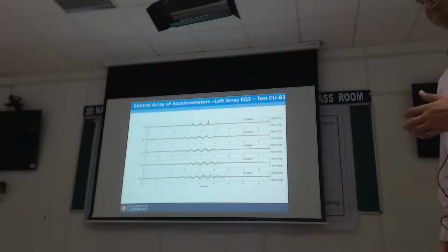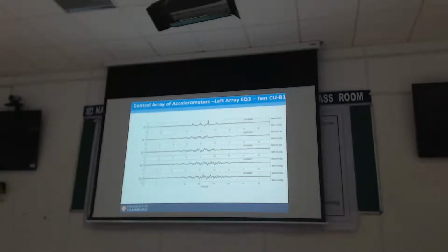Then, in order to make this slope move, we hit it with a secondary earthquake, which is 0.25 or 0.3 G. It still did not move. Then we hit it with the 3rd, 4th, and 5th earthquakes, increasing the strength. I'm going to show you the results of this 3rd earthquake, because here we are applying an input motion of about 0.5 G, and the peak acceleration recorded at the top of the slope is 0.97 G. It's almost 1 G horizontal.